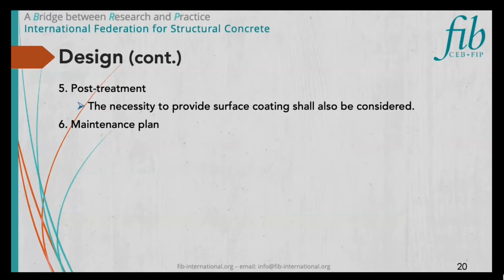If it is expected that the structure will be exposed to chloride and that the chloride amount around the rebar may increase during the remaining service life of the structure, coating material shall be selected appropriately by considering the high humidity and high alkalinity of the concrete surface due to the electrolyte.